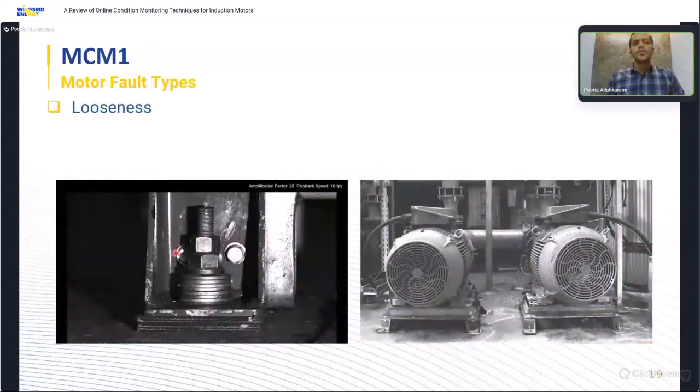We can also use vibration measurement to diagnose looseness between components in the motor foot, or the foundation, or the winding and the stator core. The core logic of this diagnosis relies on measuring the vibration, such as detecting a mass imbalance in the motor. And from the frequency spectrum, according to the laws of physics, we can detect which faults are happening in the motor.